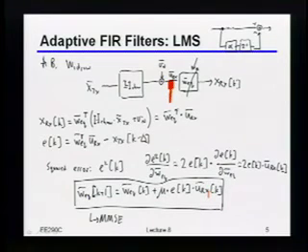The delta depends on which tap you're adapting. That's right. It's kind of implicit in this equation, in the sense that this vector here implicitly contains time in it. If I wrote that vector out, let's say if it was two long, then this would be my current sample and one sample ago. Then when I shift it to the next one, again, it's current sample, one sample previous, and so on and so forth.